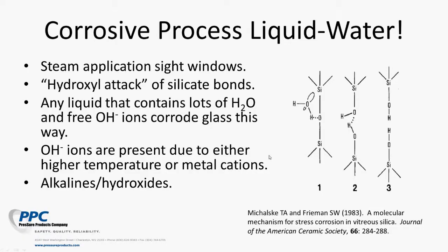Believe it or not, the fluid that has destroyed more side glasses than any other liquid is water. Of course, that's very counterintuitive since you use glass water cups at home, but you may have noticed that old water glasses lose their luster and you can't ever get them to shine again like when they were new. This is the water corrosion of glass.